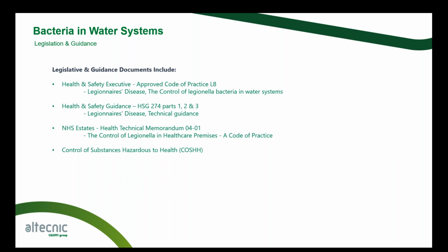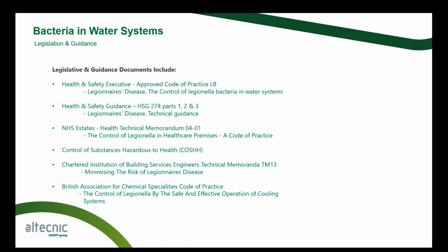The Control of Substances Hazardous to Health, or COSHH. A lot of people refer to COSHH as a sort of chemical environment, but obviously, we're talking about substances that are deemed to be hazardous to our health. And the Chartered Institution of Building Services Engineers, so CIBSE, their technical memorandum TM13, that's minimising the risk of Legionella disease. And also the British Association for Chemical Specialities code of practice, that's the control of Legionella by the safe and effective operation of cooling systems. So this is some of the legislation and guidance that sits around the control of Legionella and bacterial growth.